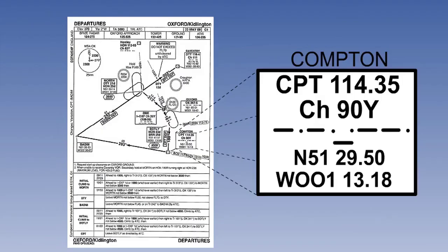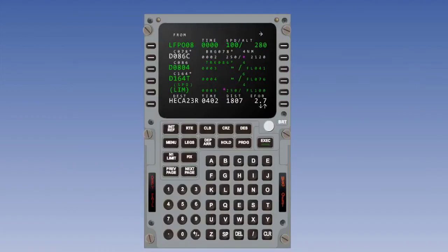A waypoint is a point on the surface of the Earth, designated by a latitude and longitude. Waypoints and VOR beacons are typically co-located to allow for either method of navigation to be used across land. But of course a waypoint could also be a point over the ocean. The pilot can also manually enter any latitude and longitude to produce a unique waypoint.